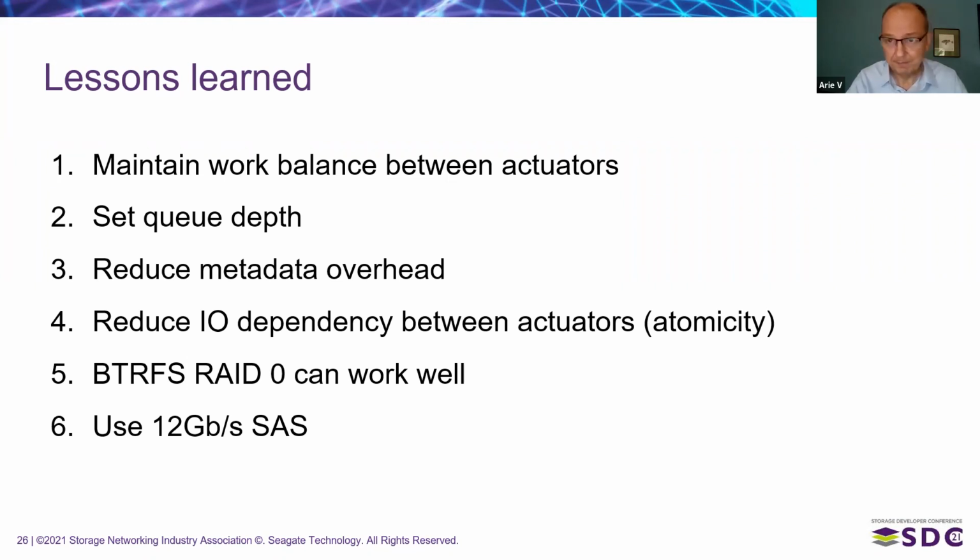Yeah, dual actuator is more of everything. When you double your sequential data rate essentially, and practically double your IOPS, what we've learned is that the other parts of the system need to increase too. You need more SAS bandwidth. You need slightly more power. You need more processors to keep these drives busy.